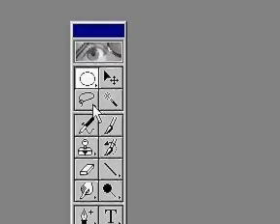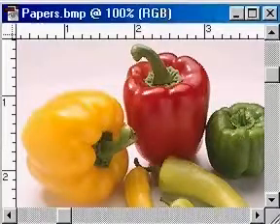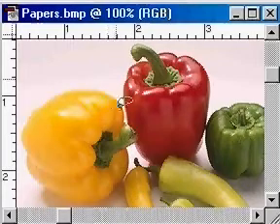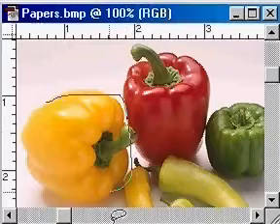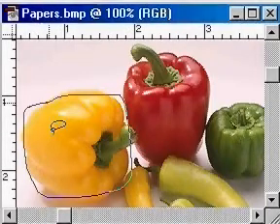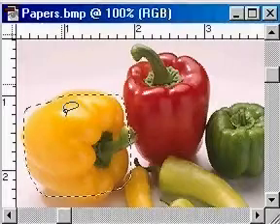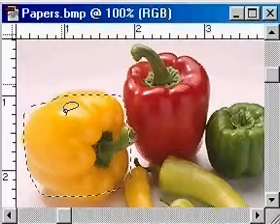Now try the lasso tool. You see this line by dragging the lasso tool around the image. You will lose the marquee by releasing the mouse. Start again. Selecting an object with the lasso tool. You need some experience using the lasso tool. You have to improve your eye-hand coordination. Release the mouse button when you are close to completely enclosing the selection.